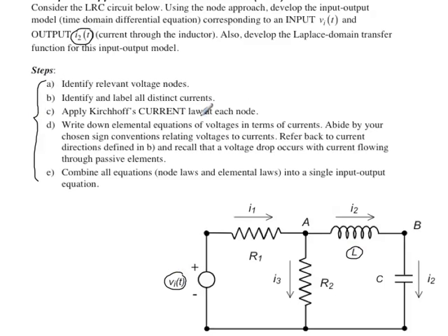C, I'm going to change this to Kirchhoff's current law and voltage law. We'll use them both, ending up with our differential equation. All the rest of it stays the same. Also, when we get through, we want to find the Laplace domain transfer function, again for the output of I2 with an input of VI.